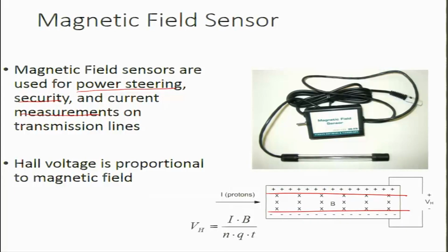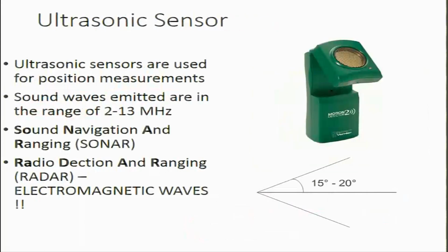So if there were a current flowing in a certain direction in which there is a perpendicular magnetic field, there would be a voltage developed at both ends of the conductor, which is otherwise known as a Hall voltage. With this measurement we could actually calculate the impact that the B field, or the magnetic field, has. The higher the B, the higher the voltage, and so on and so forth, and so magnetic field sensing can be done using such Hall sensor strategies.